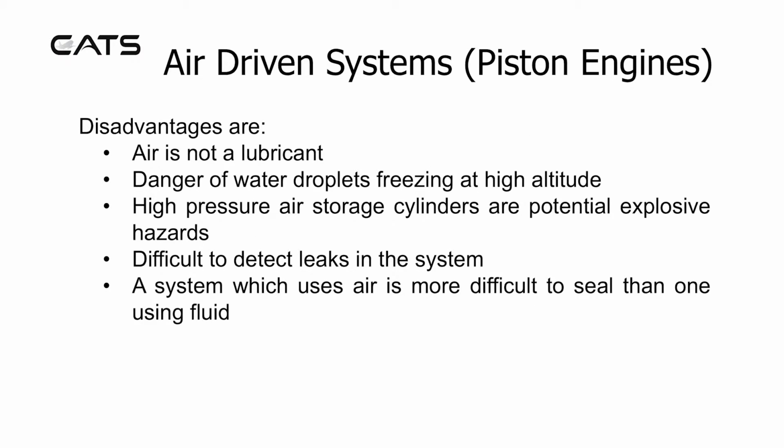The disadvantages are air is not a lubricant. There's a danger of water droplets freezing at high altitude. High pressure air storage cylinders are a potential explosive hazard. It's difficult to detect leaks in the system, and a system which uses air is more difficult to seal than one using fluid.